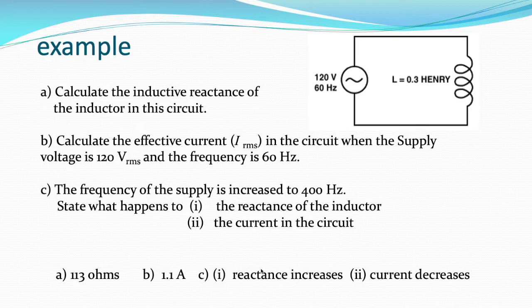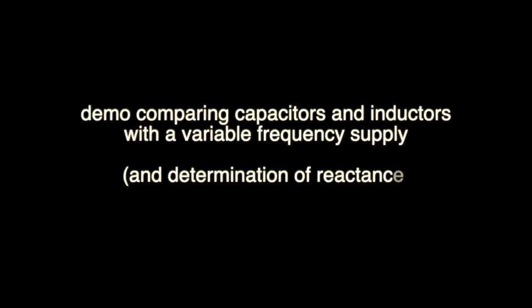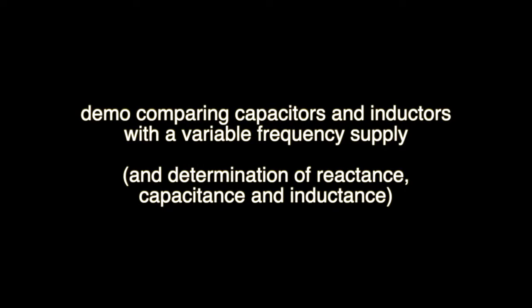So this is the opposite of capacitors. Capacitors like high frequencies. Capacitors will let high frequencies pass. Inductors don't like high frequencies, because the higher the frequency, the higher the rate of change of current, so the higher the back EMF and the greater the opposition to high frequency AC signals. Inductors like low frequencies.